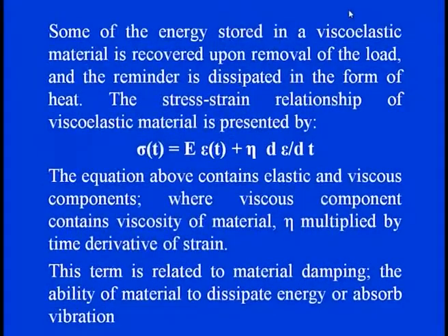And this equation consists of both the elastic and viscous features, in which the viscosity comes in terms of eta and the elasticity comes in terms of E, Young's modulus. So we can say that this is absolutely showing viscoelastic material damping, where the ability of the material is to absorb the energy and to dissipate the energy together. So this is one of the unique features of that.